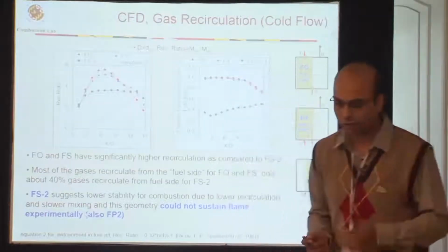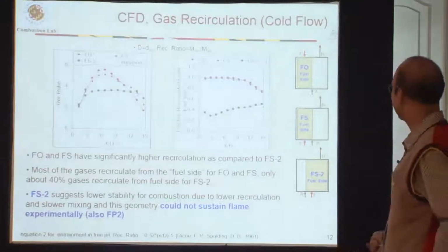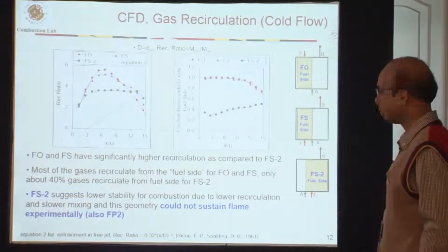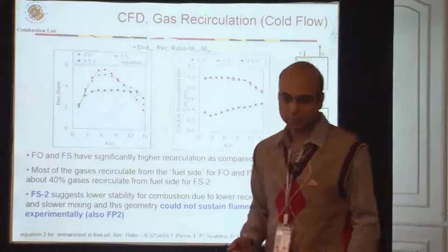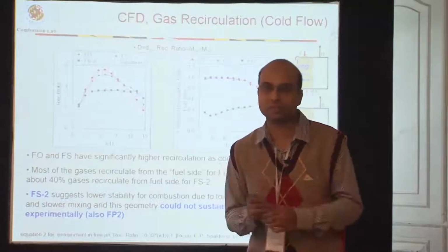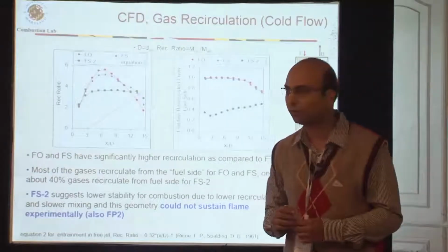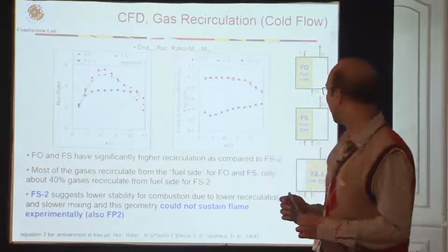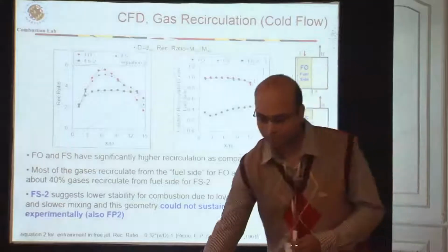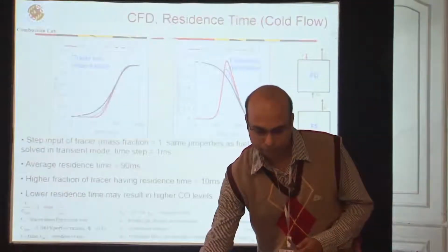So combining all these, we also found experimentally that this configuration was not supporting combustion. So this also means that you just don't have to inject air and fuel directly. You have to make sure that you have proper flow field distribution and proper gas recirculation to sustain combustion.